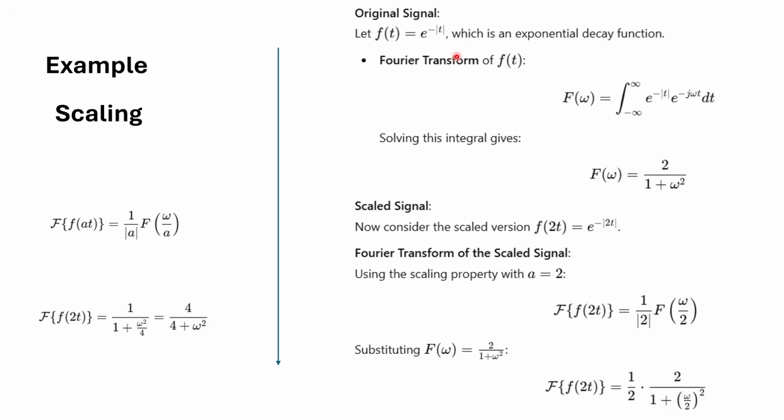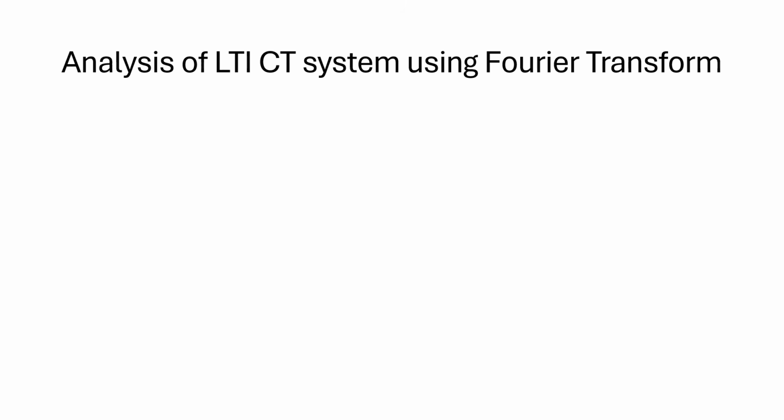So first find out the Fourier transform using the normal technique, that is multiplication with e to the power minus j omega t, and the second time you can use the property, and you will get the value of the Fourier transform. If you check, both will match. Okay. Now, so these are the properties.